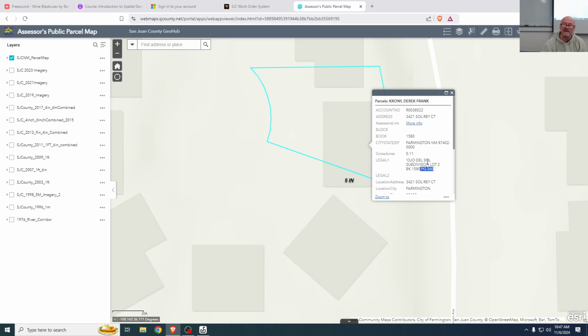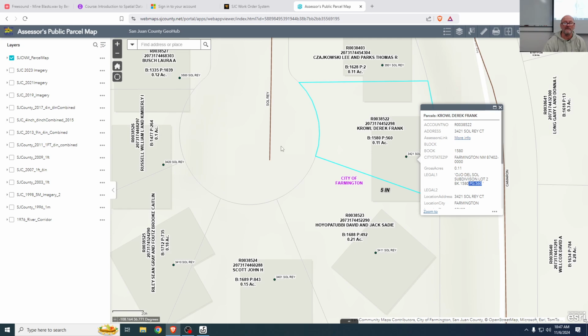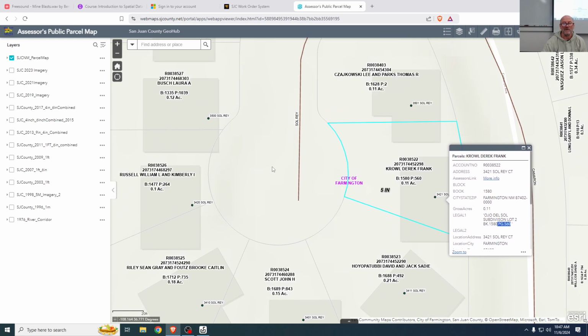On page 560, you would expect to see these lines and where they're tied into and the radius of that arc, where the center is, and these are probably radial lines from the center. Oh, here we go. So the center would be here, and this would be potentially a radial line, most likely because it's like this cul-de-sac, right? So it has probably a 50-foot radius or something. And from the center, these lines going out, maybe that line is not, but this line would be. That would be called a radial line. And then this might have an arc to it.